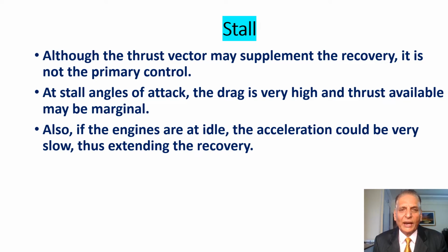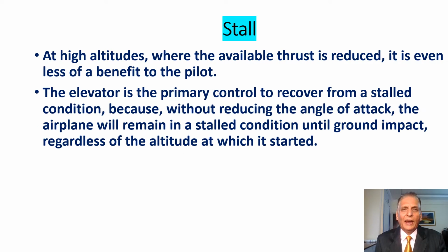At stall angles of attack, the drag is very high and thrust available may be marginal. Also, if the engines are at idle, the acceleration could be very slow, thus extending the recovery. At high altitudes, where the available thrust is reduced, it is even less of a benefit to the pilot.